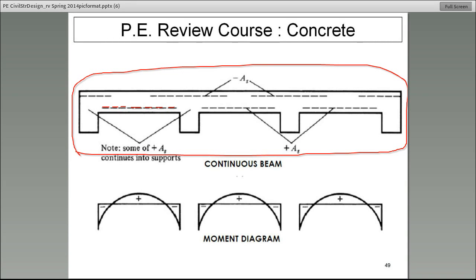What they're asking you really is to see if you recognize where you need to have the reinforcing bars. And I've already told you that. Where do we need it? Absolutely correct. On the tension side, all right? Wherever the beam is in tension, that's where you need the steel reinforcement located.